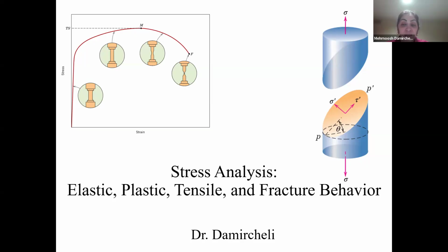Finally, we will solve a practical example using a cylindrical specimen and calculate the Young modulus, yield strength, yield strain, by using the offset method, tensile strength, elongation percent, modulus of resilience, and final sample length, and the percent reduction in area. That's percent reduction in area and EL percent or elongation percent, both of them can be used to find how ductile the material is. Okay.